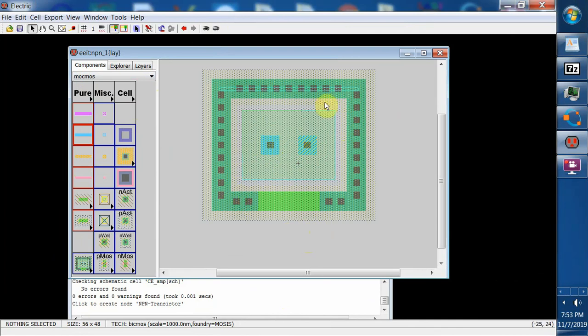And the layout for this transistor has a ring with a lot of contacts, and this ring is for the collector only. And at the entrance of this transistor and this green thing, we can route the metal across without disturbing the connectivity of the collectors.